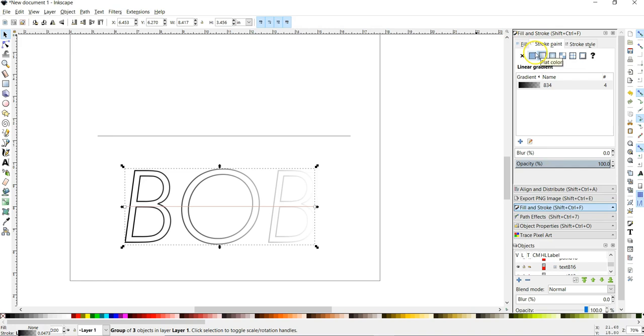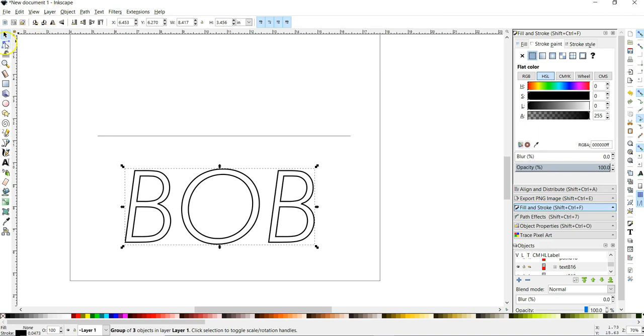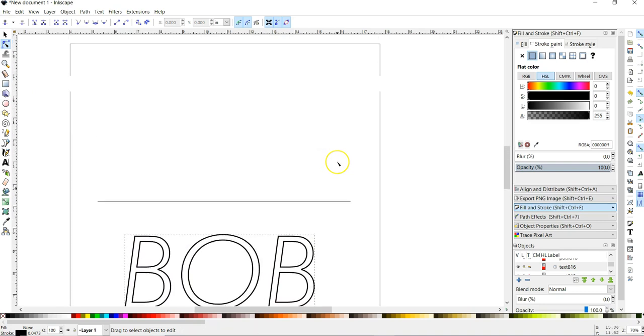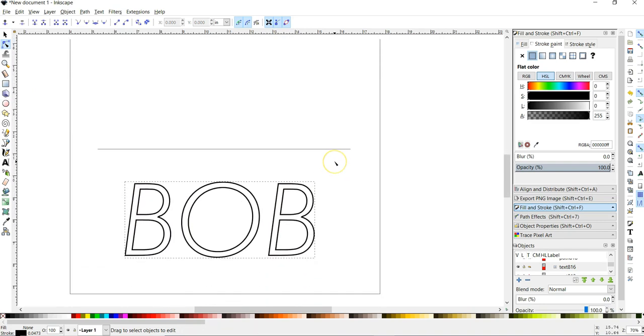It just makes it really difficult to work with on a vector platform, especially on what we're trying to do. Now, if we were to just cut this square out of aluminum, let's say, we'd run into this issue where the center of the B's will drop out of the material. All you'll have are these weird B-shaped holes without actual insides of the B's. No one wants that.